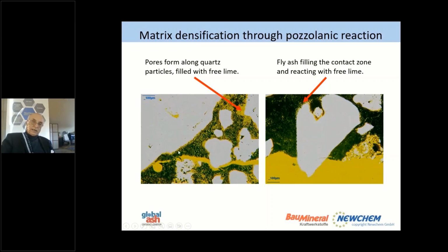If you look at the rim of the aggregate, you will see that mostly you have a rim on the aggregate because the binder will shrink and the calcium hydroxide will be the last thing precipitated on this surface. That means that if you put it in water, it will slowly swell or dissolve here, and you have a lot of ingress of material.